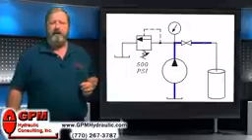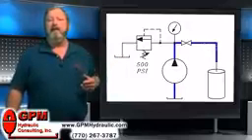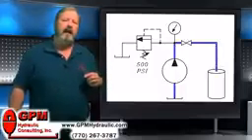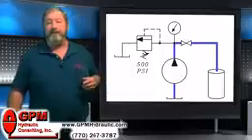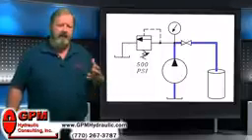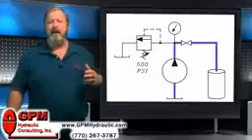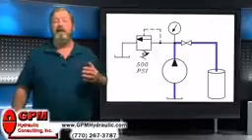So we turn the pump on, the oil goes into the oil drum, and what pressure do we read on the gauge? Well, if you said 0, you're right again. There is a little bit of resistance with the friction of the pipes, overcoming gravity and whatnot, but for all practical purposes, there is no resistance, and the gauge would read 0.